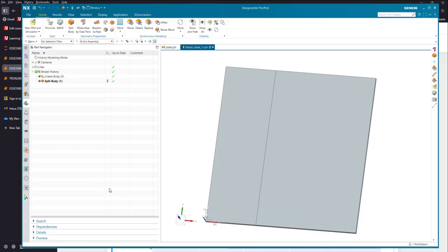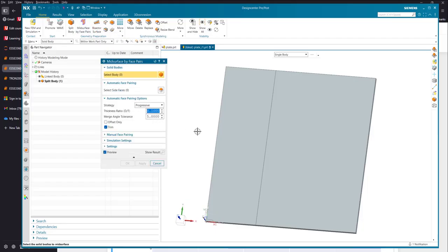Okay, perfect. The other thing we're going to do is, remember we had this beam and we meshed along the center line. This time, for our two-dimensional medium, we're going to use a mid surface. There's a tool all ready to go for this. So we choose the mid surface here, and we're going to choose both of the split bodies now.